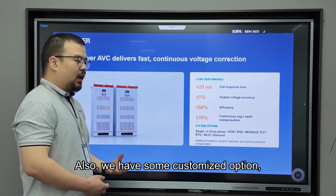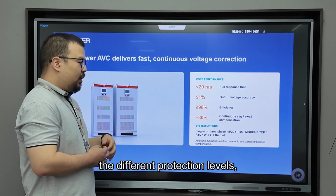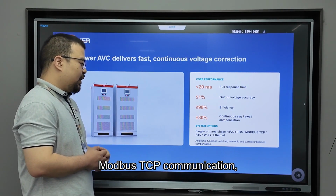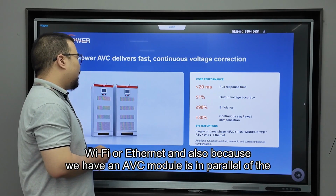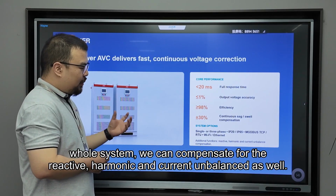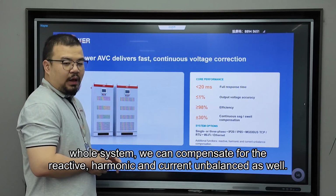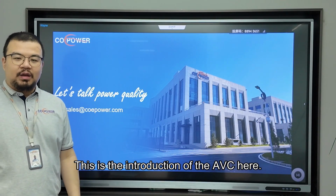Also, we have some customized options, which are single phase, different protection levels, Modbus TCP communication, Wi-Fi or Ethernet. And also because the AVC module is in parallel with the whole system, we can compensate for reactive power, harmonics, and current unbalance as well. This is the introduction of the AVC here.